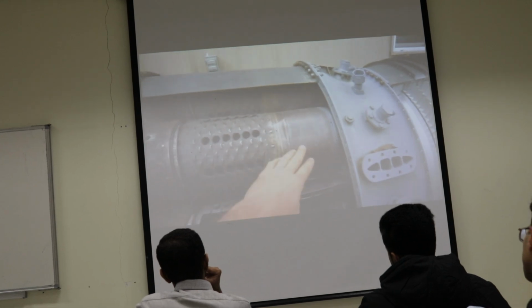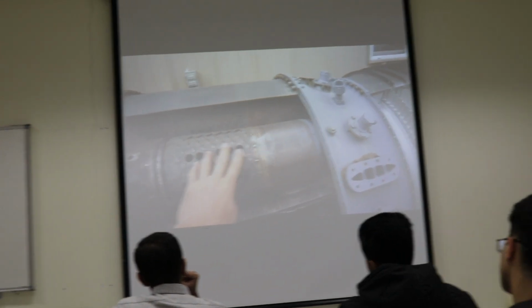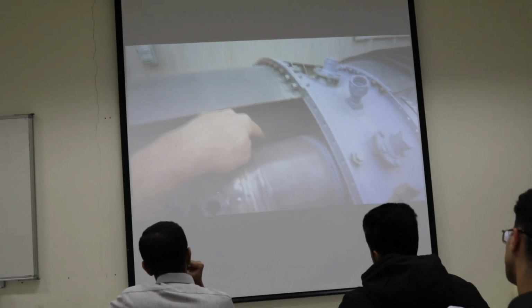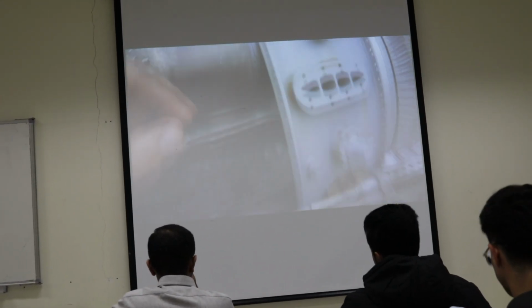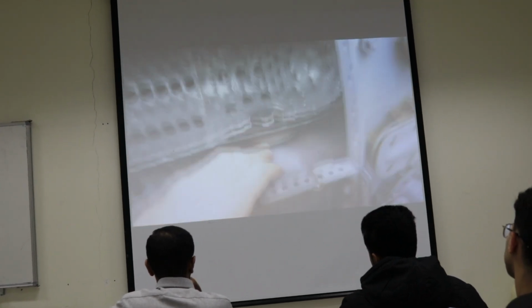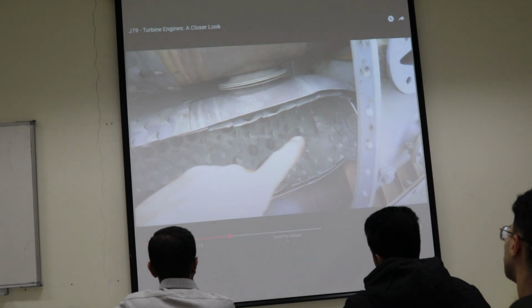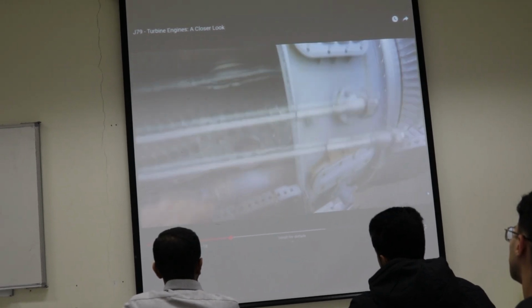Let's go back a bit. This is the mixing air holes for cooling air to mix with the flames. These are the interconnectors, for the crossfire tubes. What is the function of the interconnector, guys, here? Interconnector is doing what? Crossfire tube. Connecting the cans to each other and distributing the flame to all the cans during ignition, and also keeping the pressure constant. Constant. Yeah. Okay.